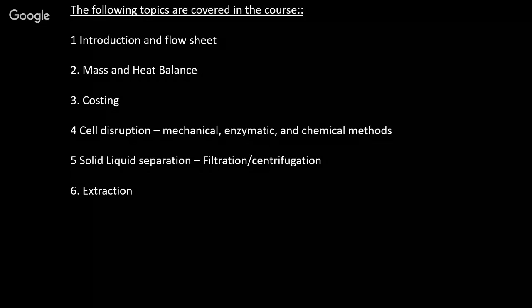If there is a cross flow situation, if there is a counter current flow situation. So given the number of stages, how to calculate the efficiency of extraction, or for a desired efficiency, how to calculate the number of stages. So we did all those calculations. We looked at the efficiency factor, and so detailed calculations were done.